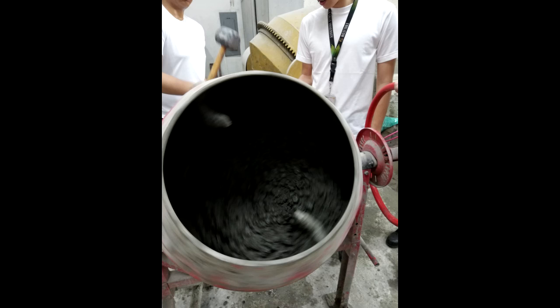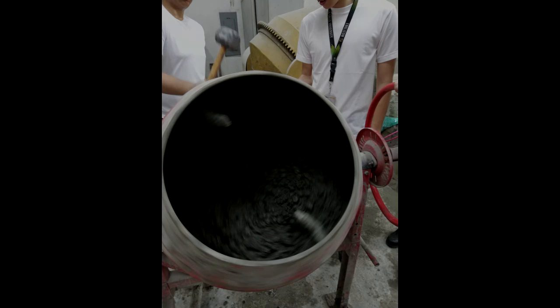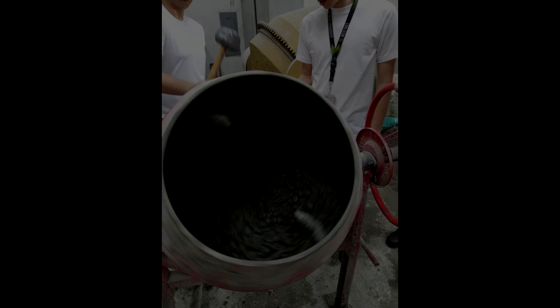The curing process is also done in this experiment and is also essential because it is the stage wherein the strength of the concrete truly develops. Curing is also done to control the desired moisture and temperature conditions of the specimen. The size and shape of the mold is determined by the type of loading that will be done on the specimen.